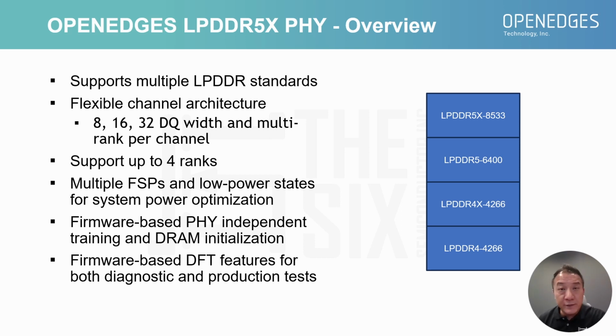Let's take a look at what OpenEdge's latest LPDDR5X has to offer. First off, we support multiple LPDDR standards, from the latest LPDDR5X backward compatible to LPDDR4. Depending on the cost-performance trade-off of your system or your family of chips, a single PHY can handle them all. Note that not all vendors support back to the LPDDR4 standard, which has a higher VDDQ supply voltage of 1.1 volt. But we're providing this flexibility with our PHY design without any negative effects on PPA.